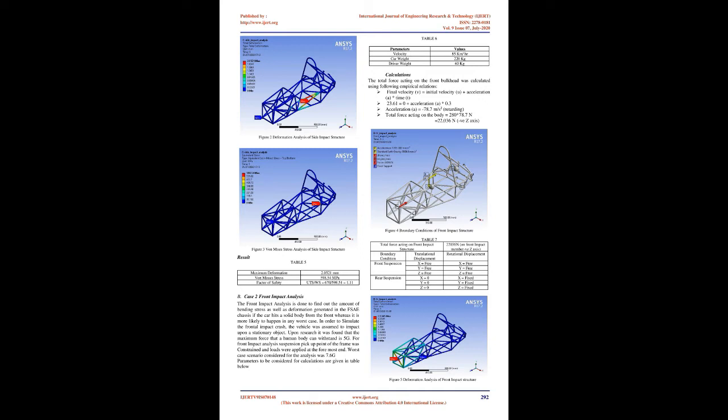A boundary condition is a place on a structure where either the external force or the displacement is known at the start of the analysis. The boundary conditions are the places where the structure interacts with the environment, either through the application of an external force or through some restraint that is imposing a displacement.